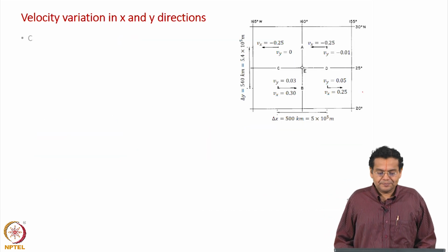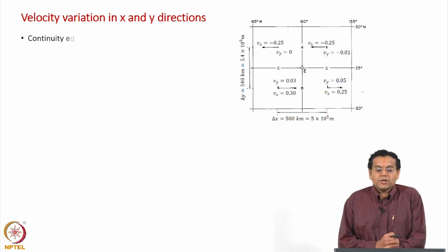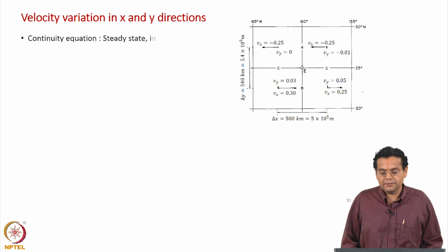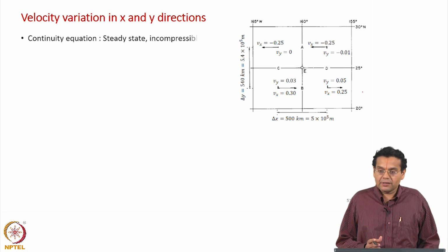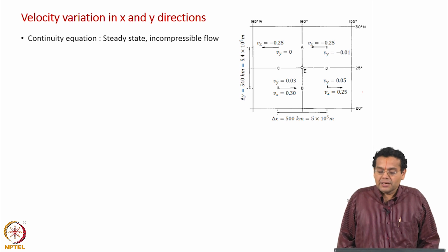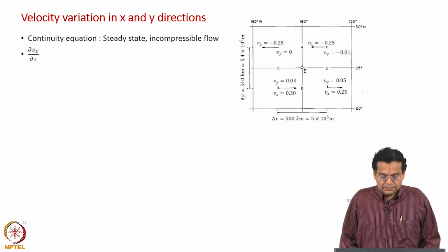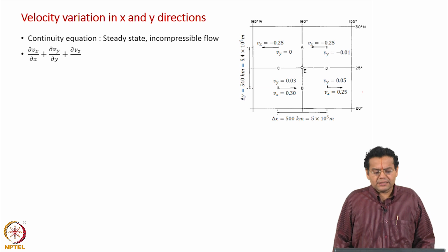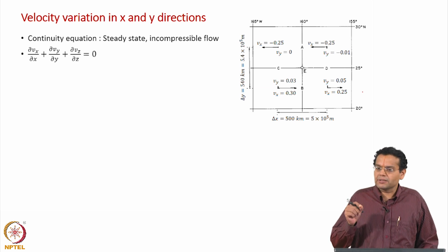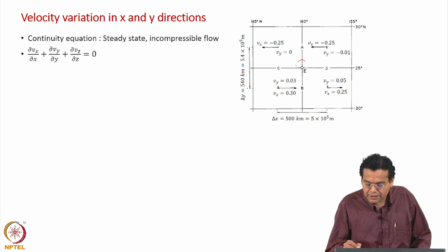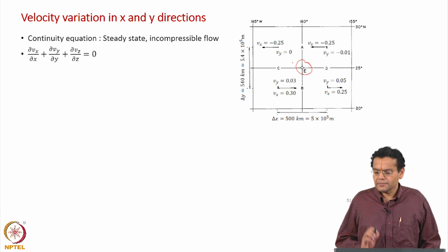Okay. Now, what is it that we are going to do? We are going to use the continuity equation. Once again, we will assume on an average it is steady state and assume incompressible flow in the ocean. And remember, it is a 3-dimensional case because we have all 3 components. We are going to apply this continuity equation at the point E.